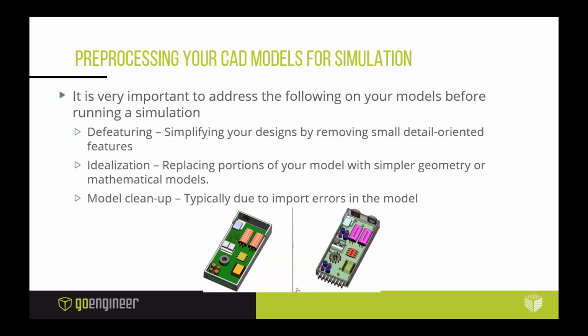And that's how you want to give yourself that insurance in the end. You'll get a ballpark figure in the beginning, right? But it's going to be easier to troubleshoot when things fail and go wrong, which they will, right? We've all been there. We all just want to throw our machines on the street, right? Sometimes. So start simple so it's easier to troubleshoot errors, then slowly start to put your foot on that accelerator and add more detail to the geometry, more detail to the setup, and more detail to the mesh. So you're converging all three aspects of your simulation. So again, that's a lot, but I like to front load that concept. That's one of the biggest concepts in all simulation.